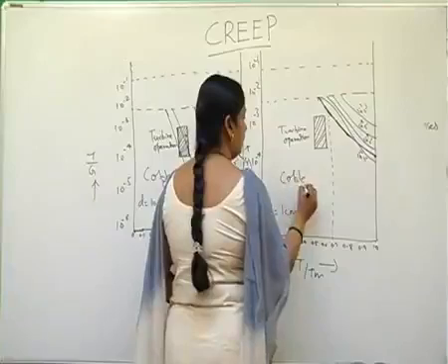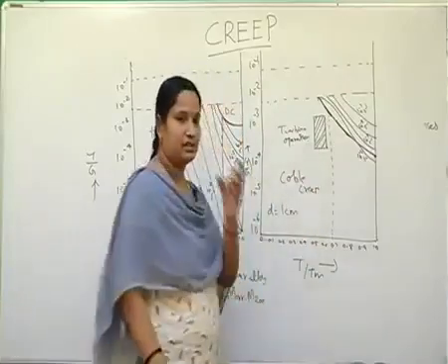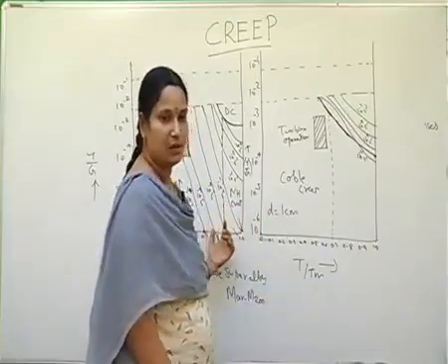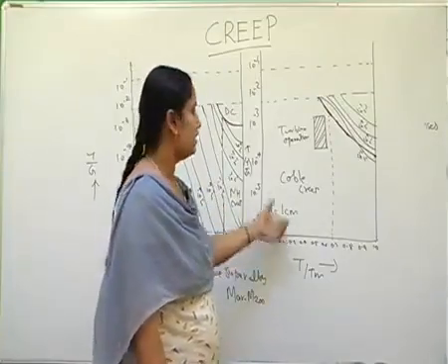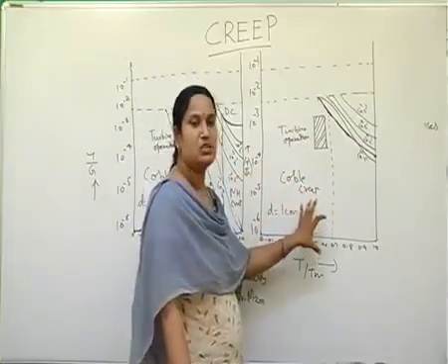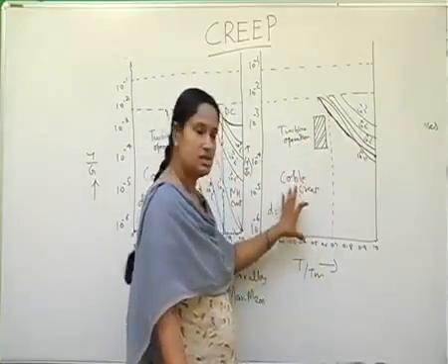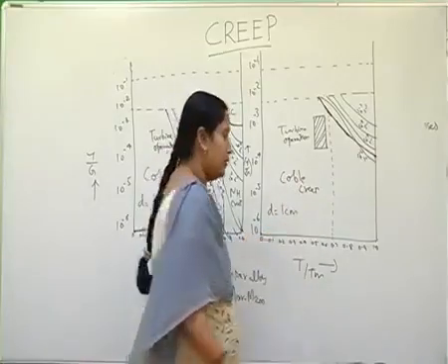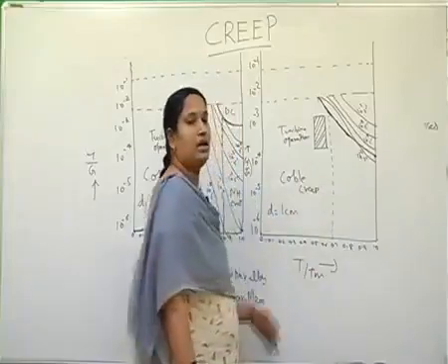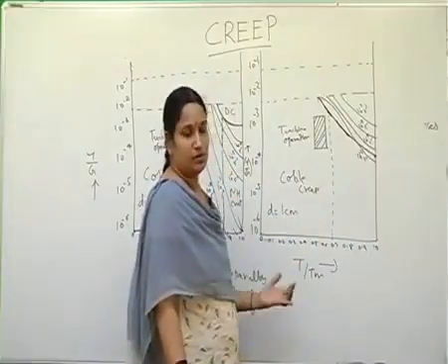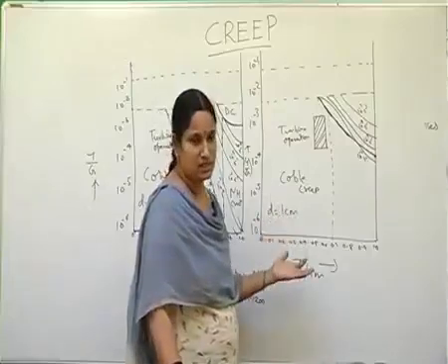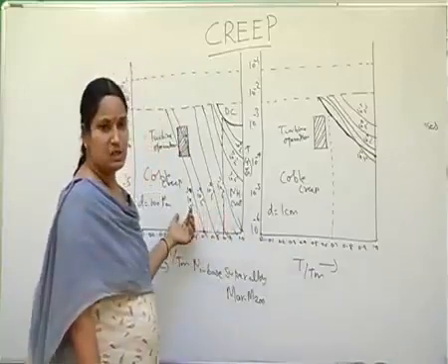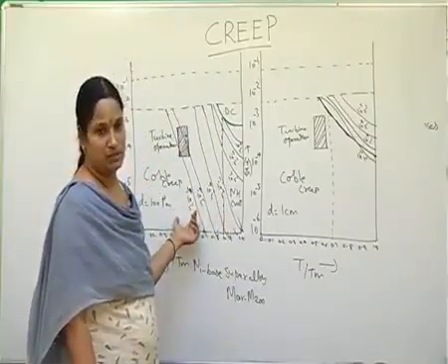By changing the grain size to a larger one compared to 100 micrometers, the dominant deformation mechanism is not changed. It is again the same, the Coble creep. But by changing to a coarser grain, creep rates are lowered. So the material has become more creep resistant with increase in grain size, compared to the grain size of about 100 micrometers.